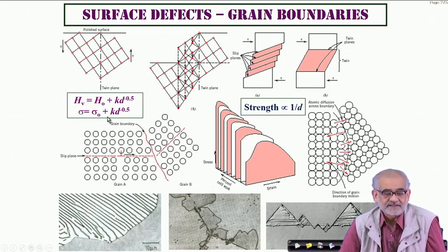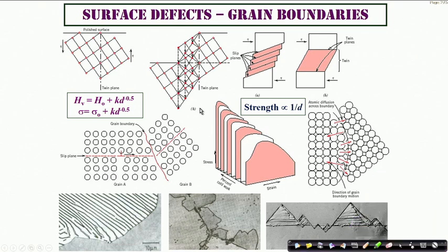So either way, this mechanical strength increases as the size of the crystallite, or so-called the grain size, decreases. And this is the famous Hall-Petch relationship, which many of you probably already know, which simply says that smaller the grain size, greater the strength of the material, and that strengthening arises purely because of the barrier posed by these boundaries to dislocation movement.